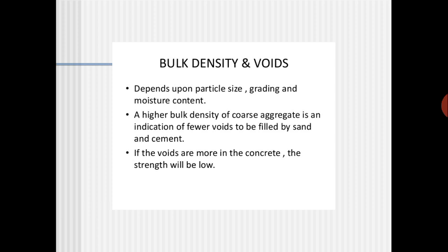Some sufficient void should be there, and it should not be more, and it should not be less. So some constant range of void should be maintained, so that proper cement and sand can be placed in between the voids that are present in the concrete. If the voids are more in the concrete, the strength of course will be low.